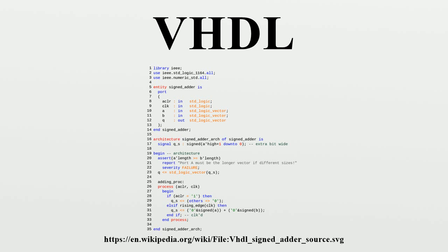Latch template. A transparent latch is basically one bit of memory which is updated when an enable signal is raised. Again, there are many other ways this can be expressed in VHDL. Latch template 1: Q <= D when enable = 1, else Q. Latch template 2: process begin if enable = 1 then Q <= D; end if; end process.